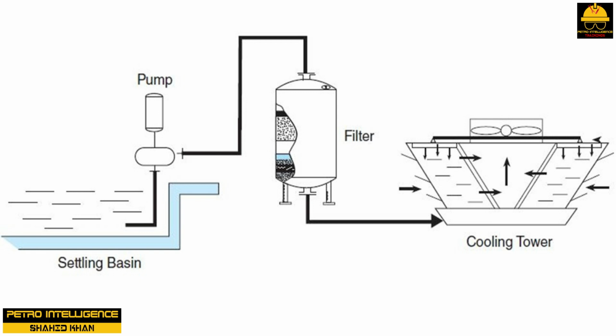Surface water, water that is drawn in from lakes, rivers, and oceans, must be treated before it can be used. Water treatment systems are designed for that purpose. A series of large pumps take suction off the basin and send water to a series of filters for additional purification. Some filtered water is sent to demineralizers for additional treatment to remove dissolved impurities.